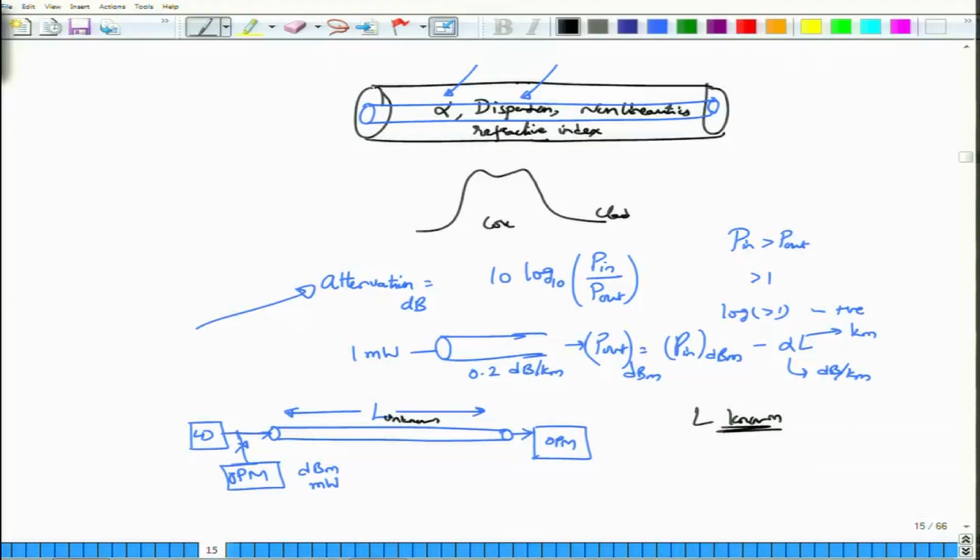Next what you do is you cut a known section of the fiber, and this can be done in a much more controllable manner. That is, you can actually take a ruler and align it along the fiber and get accuracies to just about a few millimeters. So, you can cut this and then remove the cut portion and reinsert the optical power meter to the original length.